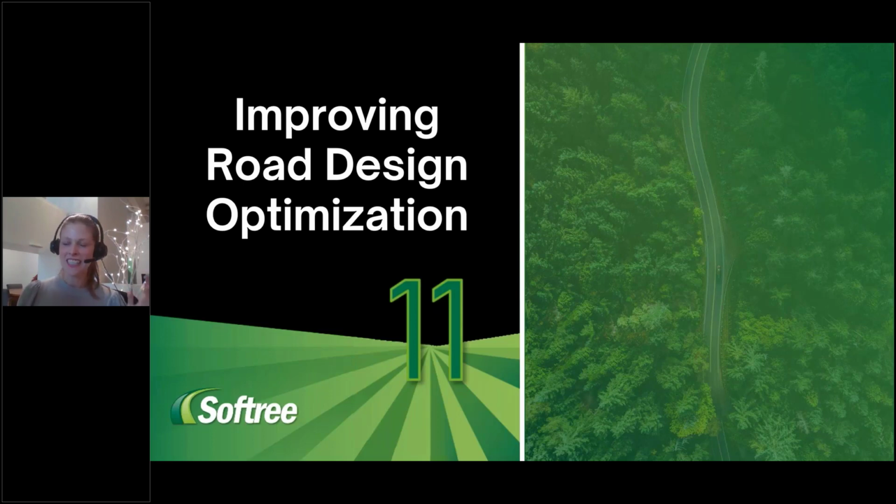So to get started, let's talk a little bit about what a greenfield road design workflow with our optimization tools now looks like inside of RoadEng. So you start by importing your data. This is high resolution data like LiDAR or drone data. We create our tin surface, and then we're trying to determine the best road location, either manually or out in the field. So we've got techniques like road pegging you can use. Maybe you've got a preliminary alignment that you've figured out in GIS. So you're determining that best road location.